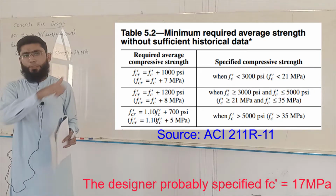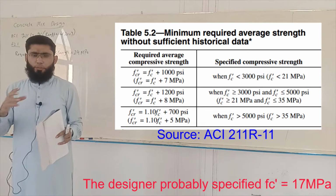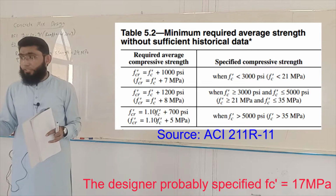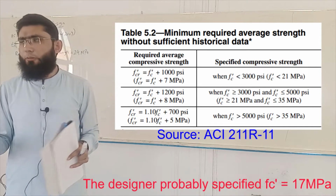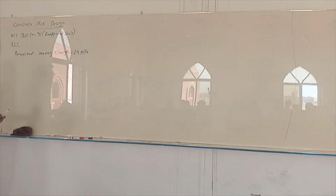So it means that the specified value was something lesser than this, and there's a way to get this value. You can use either the previous data and the standard deviation of the previous data, or you can use a simple value. I'm going to share that equation some other time with you. So right now, what we're saying is that this is the required average strength. This is not the specified cylinder strength. Specified cylinder strength is some value lower than this.